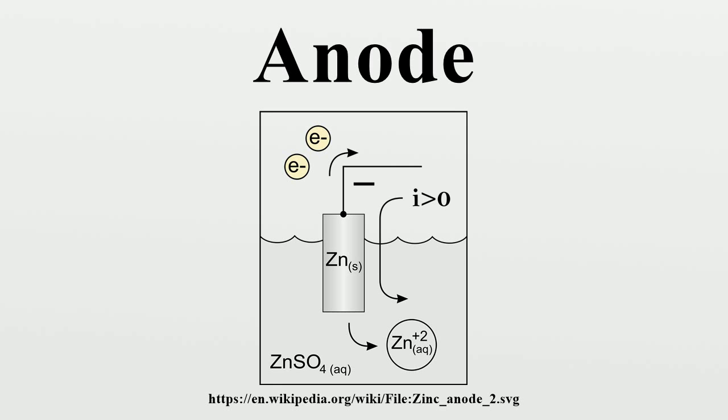In the United States, many battery manufacturers regard the positive electrode as the anode, particularly in their technical literature. Though technically incorrect, it does resolve the problem of which electrode is the anode in a secondary cell. Using the traditional definition, the anode switches ends between charge and discharge cycles.